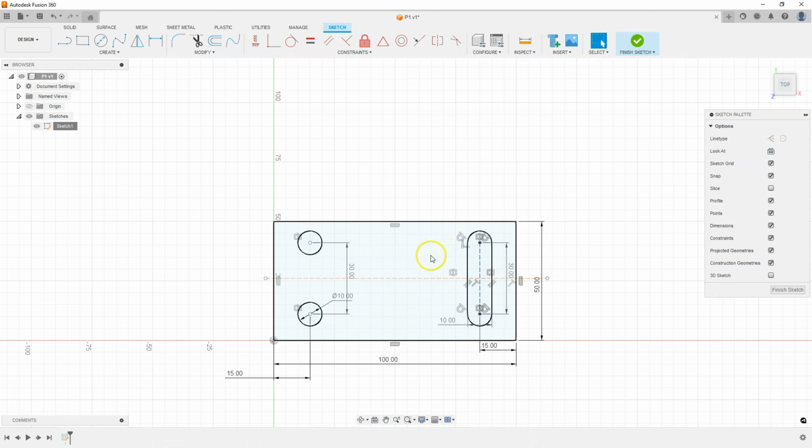Press Escape to cancel the dimensioning command, and it looks like we have all the dimensions added, but the geometries are still blue. Here the geometry of the rectangle is only black, and black geometry means that the sketch is fully defined, that is, it is fully dimensioned and related, which means that we can no longer freely change this sketch. This makes it more difficult to accidentally damage the geometry, and as for the slot and the circle geometry, they are not fully defined.